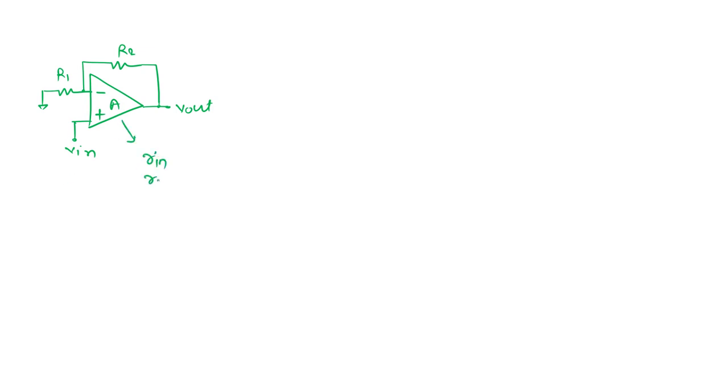Why am I so concerned about this? Because for this structure we must have two conclusions. If the input is here, that is a non-inverting structure, then the result is that simple. To arrive at this result, I have taken this approximation on the previous page. If my amplifier has input impedance Rn and output impedance Rout, then the input impedance looking from the source is Rn times 1 plus A beta, where A beta is the loop gain that we know.